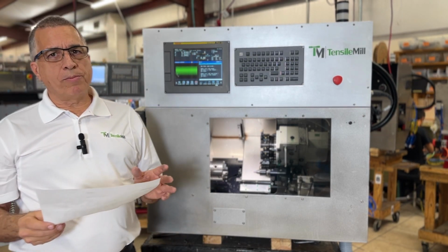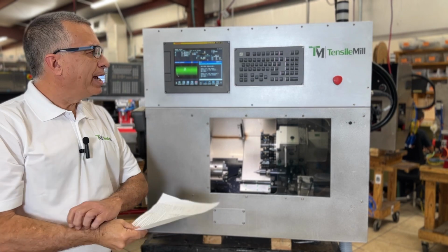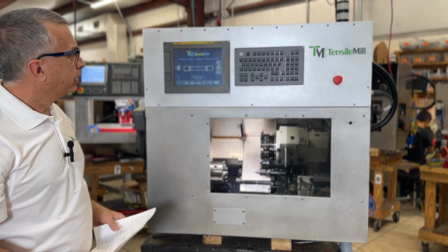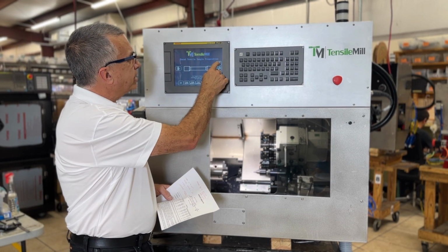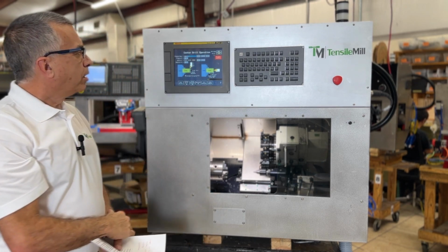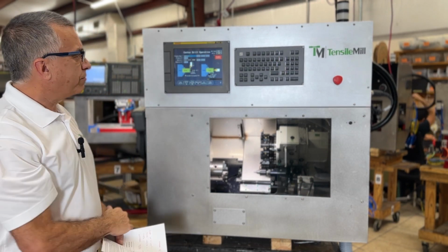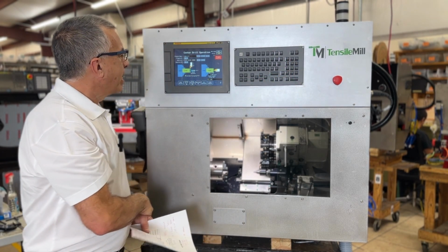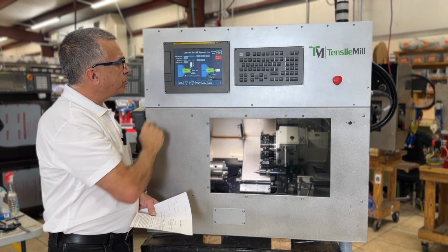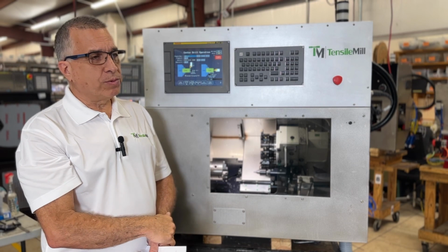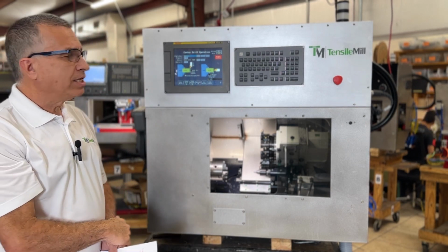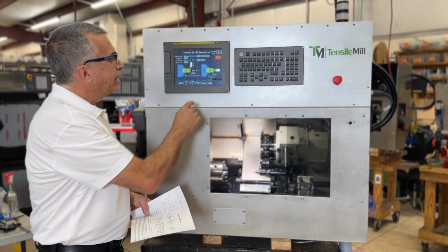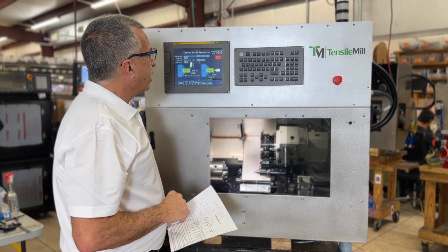Okay, once we are sure what the part looks like, we can now go ahead and do the center drilling. Go back to the Tensile Mill program, TensileSoft, and we choose center drill. We only have to specify two things here. We have to specify the stock diameter, 0.625, for example. And then we have to turn this square on, which is actually telling it to face. We don't have to face the part, but it's a good idea to face it to make a nice transition from the tail stock to the front of the part.